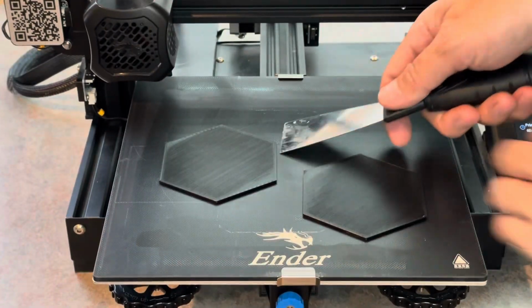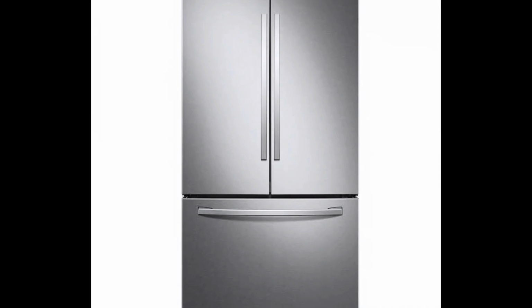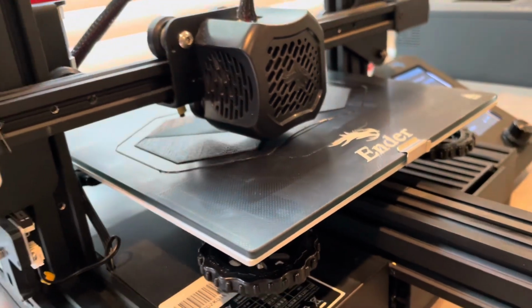Once the print is done, carefully remove it from the bed. If it's stuck, place the entire bed into your freezer for 20 minutes and then try again. This usually does the trick. And that's how to use a 3D printer.